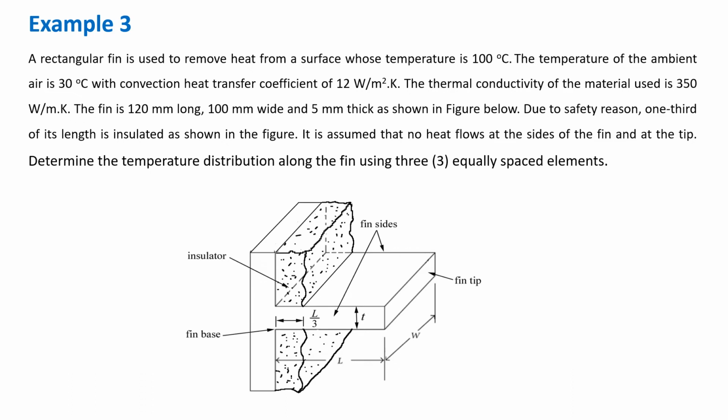Here is the interesting part. Due to safety reasons, 1/3 of its length is insulated, as shown in the figure. It is assumed that no heat flows at the side of the fin and at the tip. Determine the temperature distribution along the fin using 3 equally spaced elements.